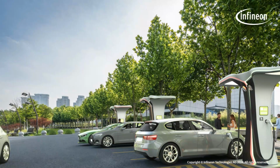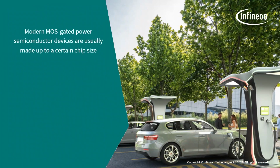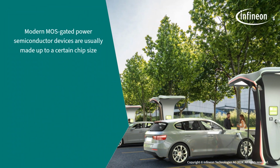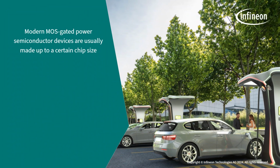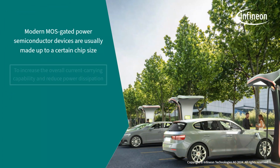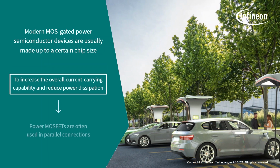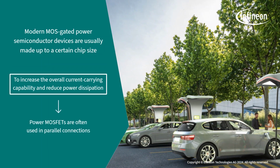Unlike power diodes or thyristors, modern MOS-gated power semiconductor devices, like IGBTs or MOSFETs, are usually made up to a certain chip size due to the production yield consideration. Therefore, to increase the overall current carrying capability and reduce power dissipation, power MOSFETs are often used in parallel connections.